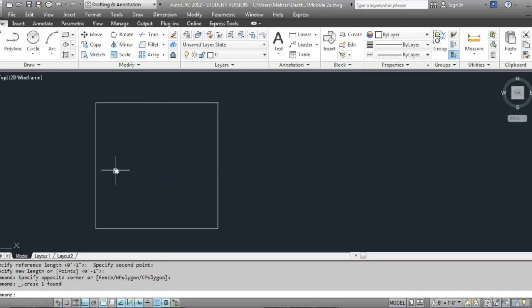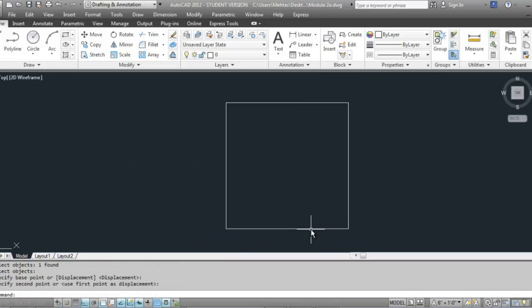Say you wanted to scale this object disproportionately. Say you wanted to make it longer along one side. Then you would have to use a command like stretch. Now this is where the stretch command is a little different. When you click on stretch, the keyboard shortcut for that is ST. You still get a pick box, but if you click the box and select the entire box and hit enter and then use the stretch command, it is only going to move the object.